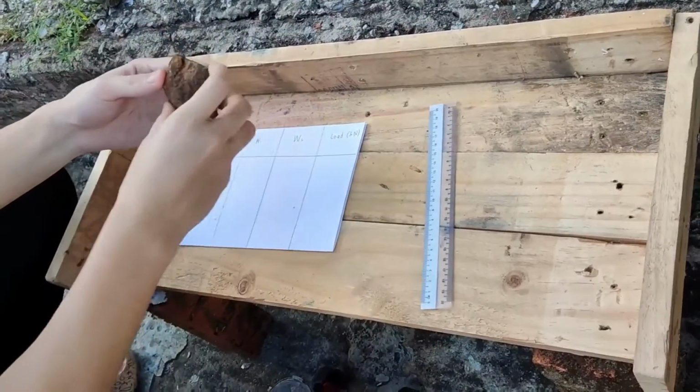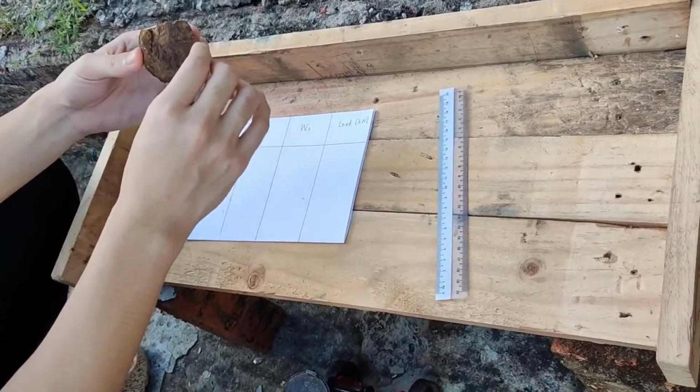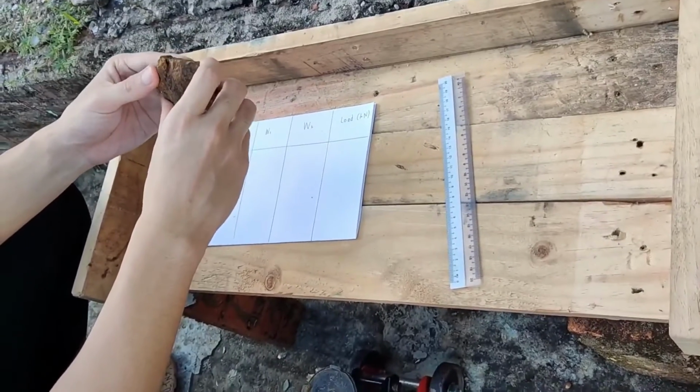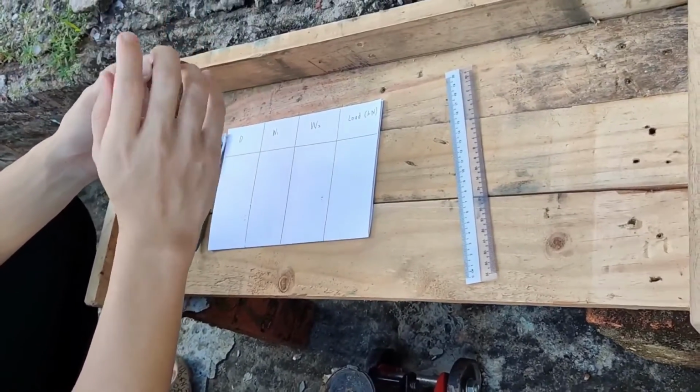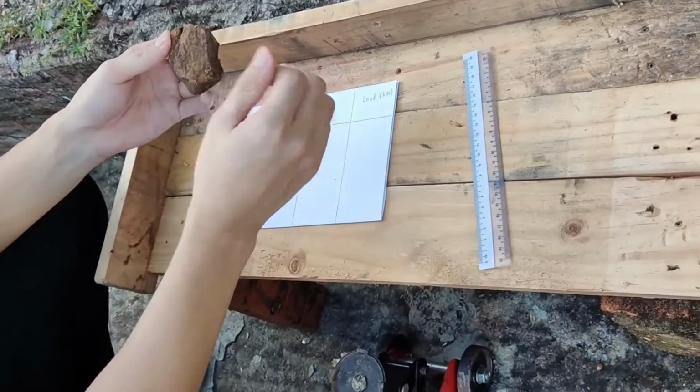As we can see from here, this is a very beautiful rock sample. The rock samples could vary in size and shape. There is a recommended size. According to ASTM D5731, the dimension of the rock should never exceed 85 mm. It should be between 30 mm to 85 mm.